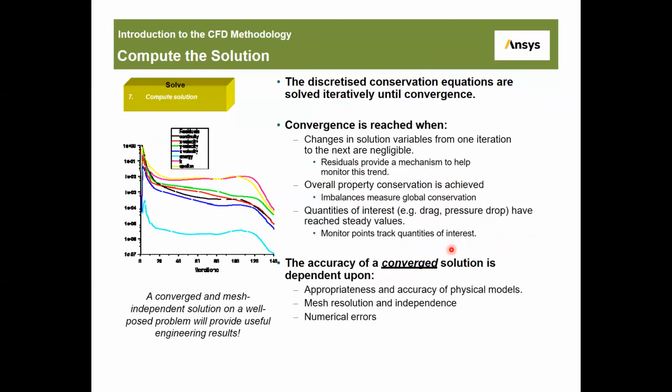All right, and then you need to compute the solutions. Once we have set the boundaries, we have set the velocity at the inlet, how much the velocity is at the outlet, how much the temperature, how much the pressure, we set all of them, and then we need to compute the solutions. When you compute the solution, it will solve the equations we told it about here,